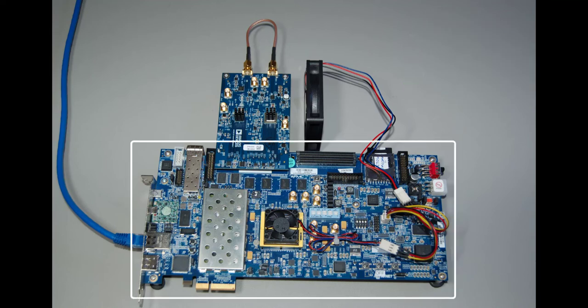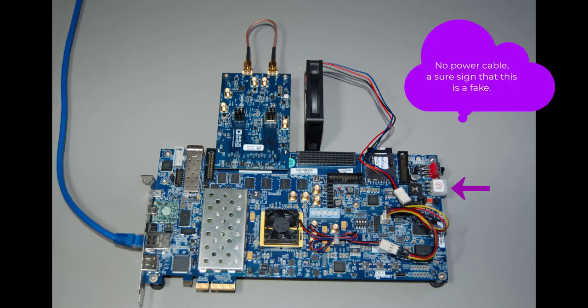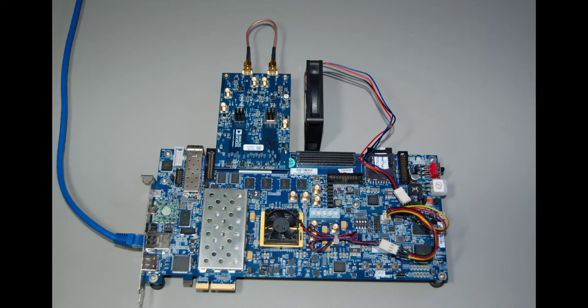The host board is a Xilinx ZC706 with an Ethernet connection. The ZC706 is running Analog Devices IIO software. The FMCOMMS11 board has an input and output sample rate of 1.96608 gigasamples per second. This is the sample rate for 5G, so the board is set up ready to go for 5G signals.